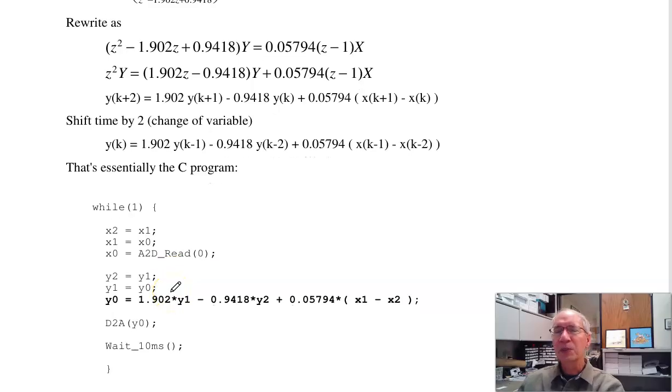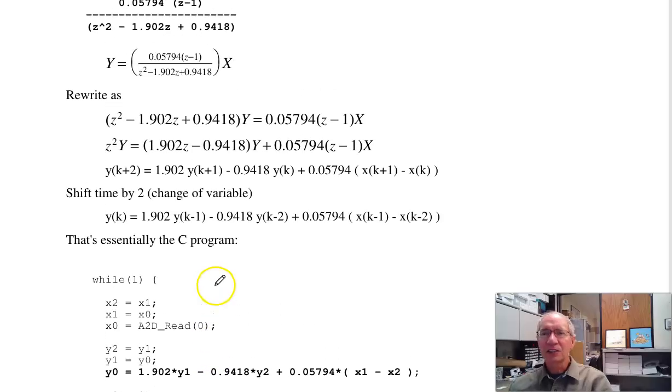So this is kind of the point behind Z-transforms. If you ever want to implement a filter in software, the proper way to do it is convert to the Z-plane and then implement that filter in the Z-plane. Advantage of filters in the Z-plane is I can implement that exactly. So there's no approximation here. This filter is exact.